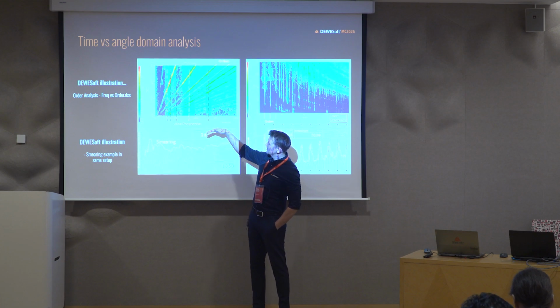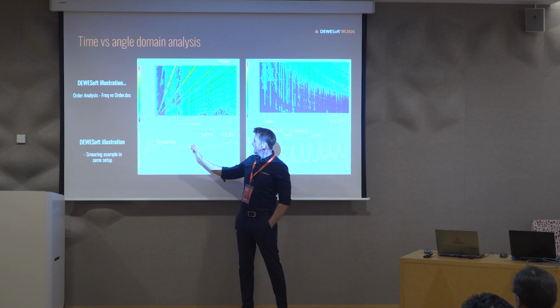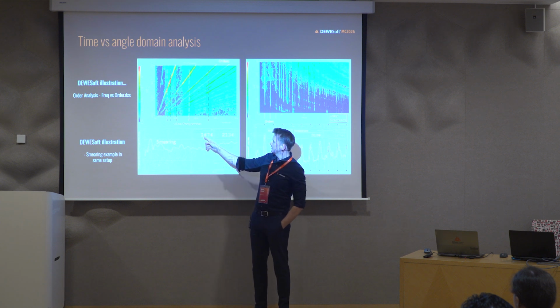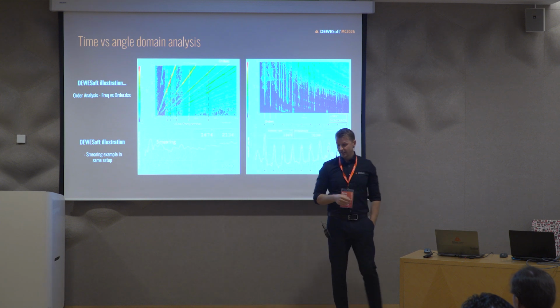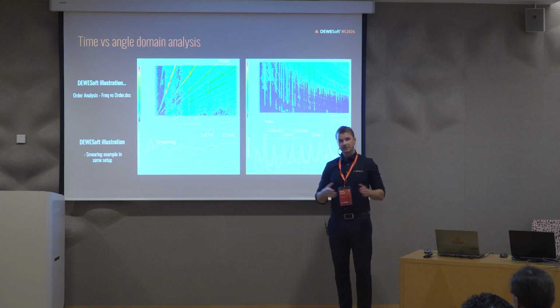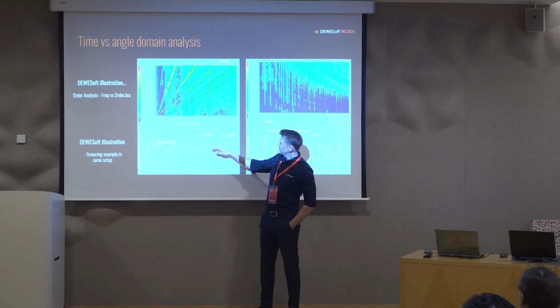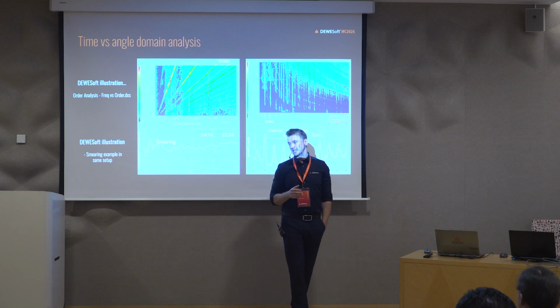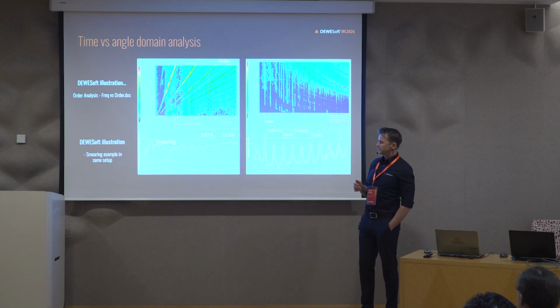You might have that binned in for certain speeds, but if you're having a run-up, like here, let's say it goes from 1600 to 2100 RPM, if you're averaging over that, the red curve here shows you that it will be smeared. You cannot really follow in a great manner a good signal-to-noise ratio on those components because of that.